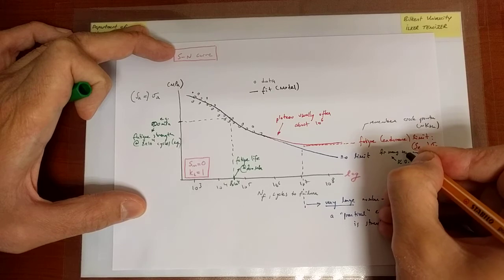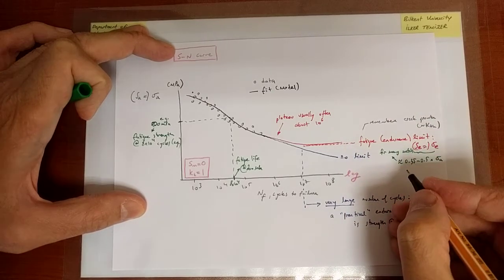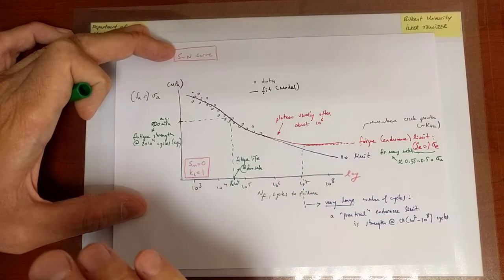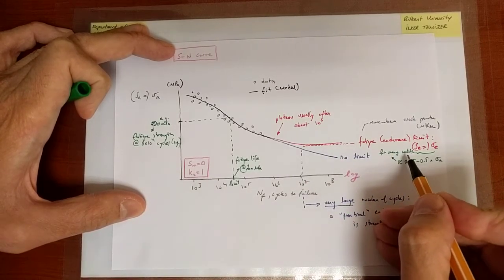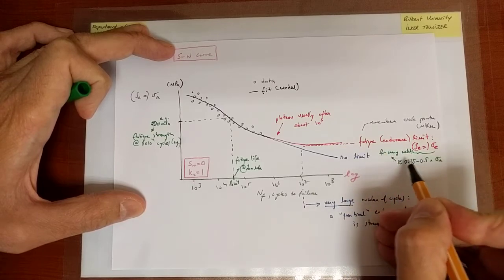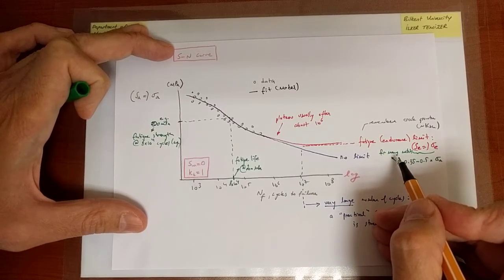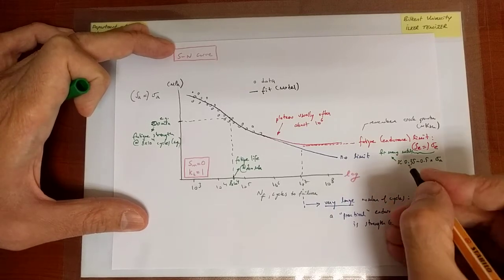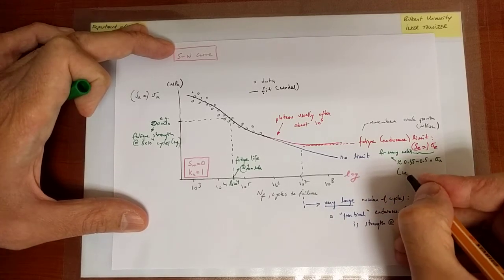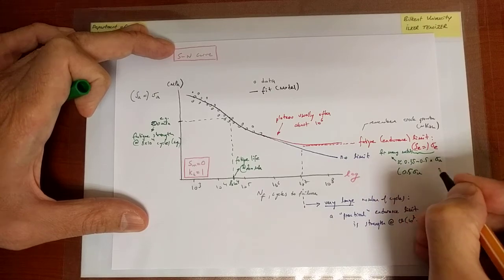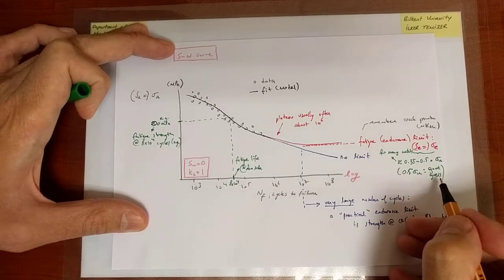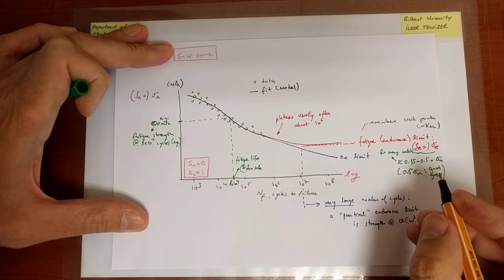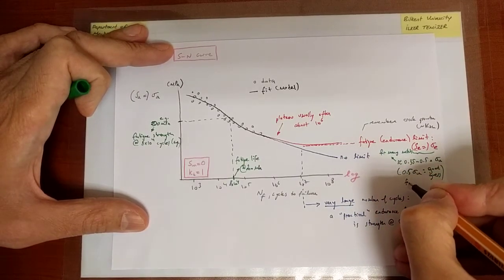On the other hand, if you know that there is an endurance limit and you don't exactly know the value, so the value might be stated in tables of material properties, but you want to guess what it is, a good value to start from would be half of the ultimate strength. This is a good guess for, let's say, either accurate or quick back-of-the-envelope calculations for most steels.